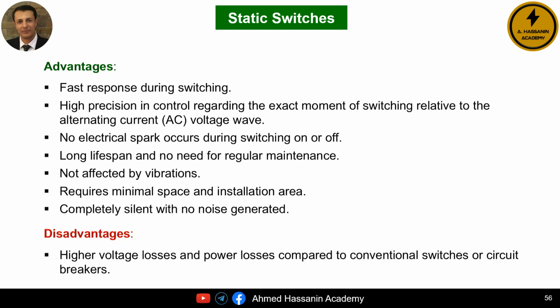Among the advantages of static switches, first, the fast response in switching, connection and disconnection. Second, we can precisely control and select the exact switching moment with respect to the alternating voltage waveform, meaning we can choose to switch during the positive half cycle or the negative half cycle, which results in extremely accurate switching. Of course, these are electronic switches, so there is no electrical arcing during switching. Also, they require no periodic maintenance, which results in a long operational lifespan. In addition, there are no moving parts, so they are unaffected by vibrations and produce no noise or sound.